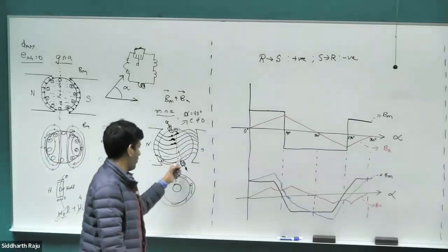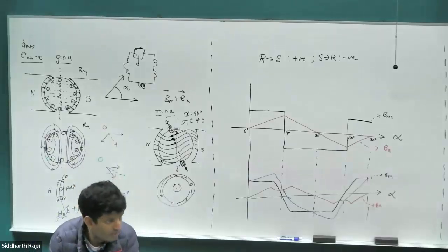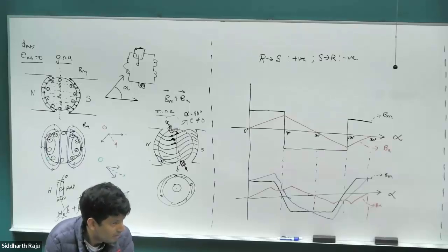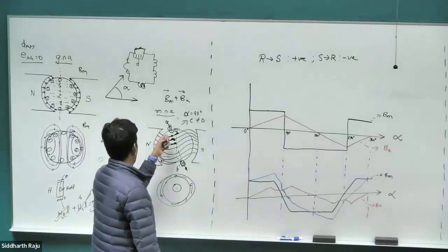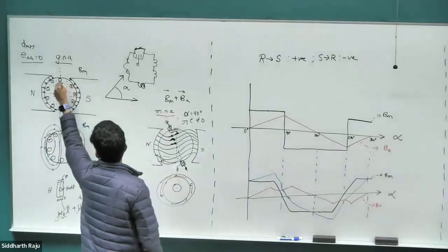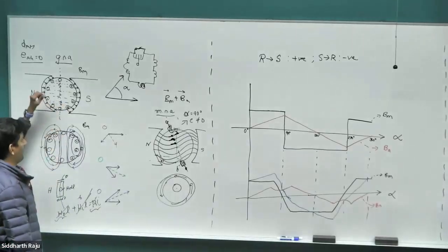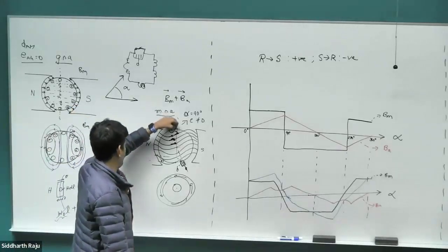So this has its own problems. What are the problems with shifting the brushes? If there isn't current going through the core, then you are in the same situation, just reversed. Perfect. So if we don't have any current in this conductor, the magnetic neutral axis would align with the geometric neutral axis, which was this ideal case that we saw, where the rotor current carrying conductors are ignored, right? And if the current is very small, it will be very close to the geometric neutral axis.